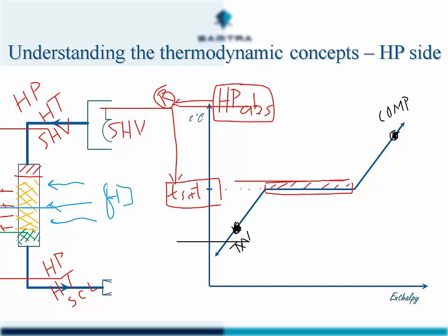Where the condensation will be taking place. So again, from a pressure gauge, we will get the high pressure. From the high pressure side, we need to go to our vapor tables to get the saturation temperature. What we need to do is to be able to measure the temperature after the condenser. So that would require a temperature sensor of some sort. So we would have a temperature gauge mounted or temporarily installed to measure the temperature.